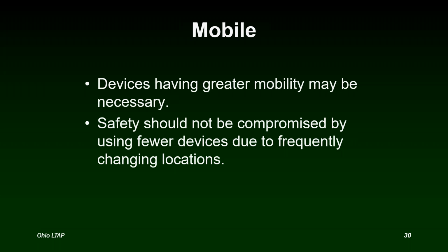And of course, one of the standards of mobile work zones is your high intensity lighting. So you really need to have a good set of high intensity lights, flashing strobes. And we're not talking about your tailgate flashers. We're talking about real high intensity strobes, flashing lights. I know ODOT recently updated our requirements for our high intensity lights. So we call it our 360 lighting package, so that the high intensity lights are visible from all directions, and it usually has high intensity strobes on all corners of the vehicle plus a light bar across the top that's high intensity.